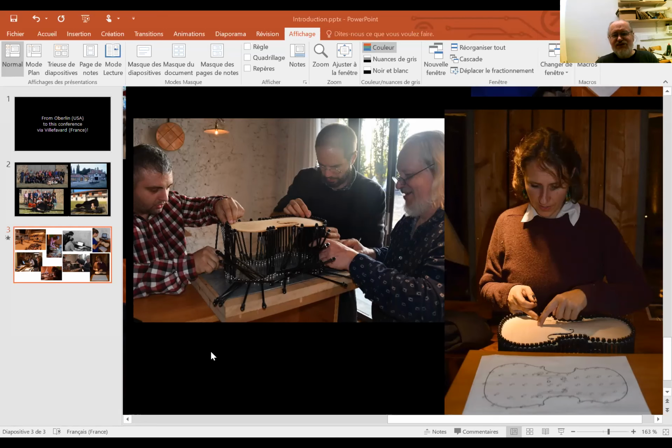Well, the idea is that we're trying to remove one degree of freedom, that is the vertical motion at the edges, and we're trying to minimize the clamping and resistance to the perimeter spreading and shrinking. Of course, it's impossible to do that perfectly, but it's a question of to what degree you manage to achieve that state. Another reason is that in finite element modeling, this is a very clear-cut condition which somebody working with FEM can model.